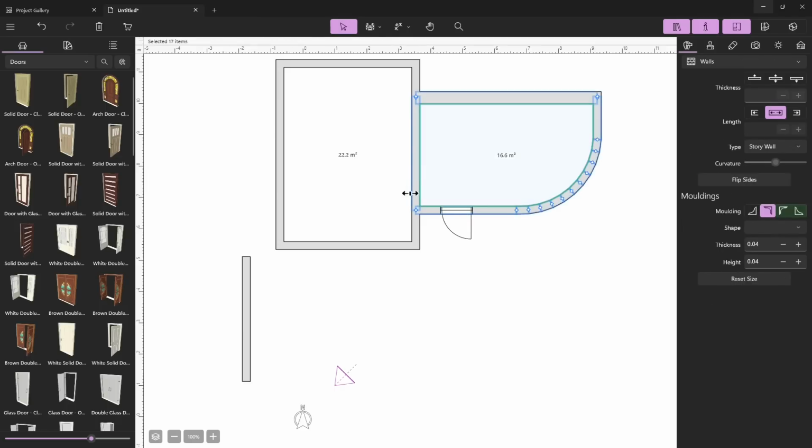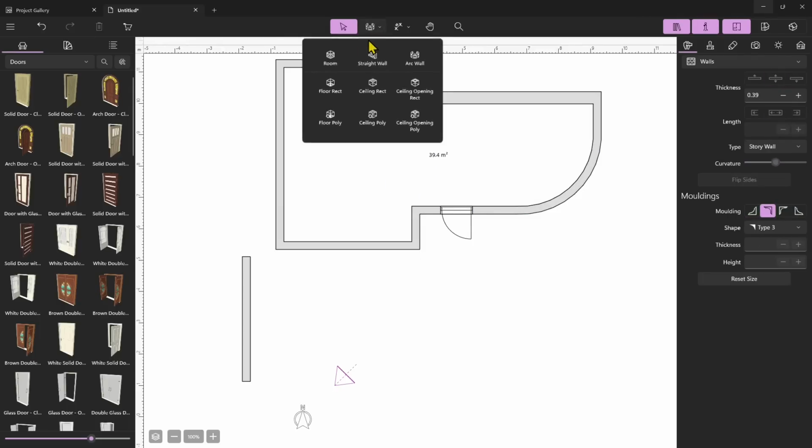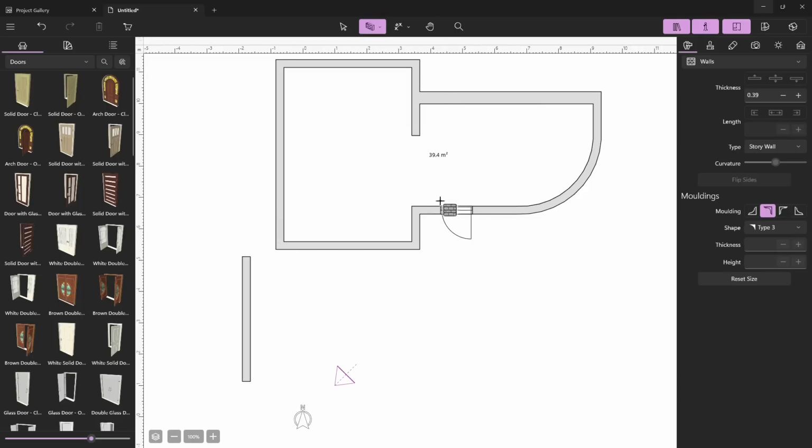The other way is, if I want to create an aperture between these two rooms, I can just click and drag here and make a space to pass through. And then maybe I can create another piece of wall from here, and that's the aperture right there. And well, this is not the same width, so it needs to be fixed. So to fix it, I'll select it and do 0.25 and press enter.